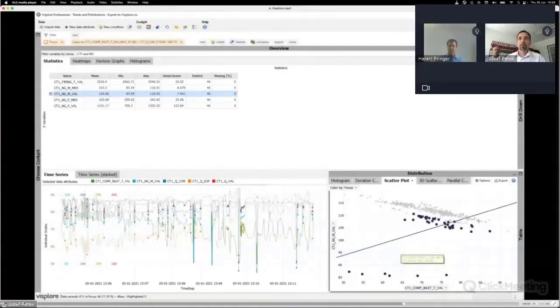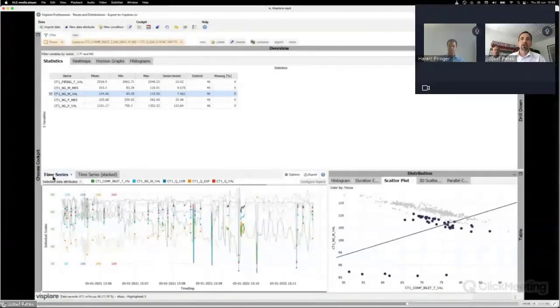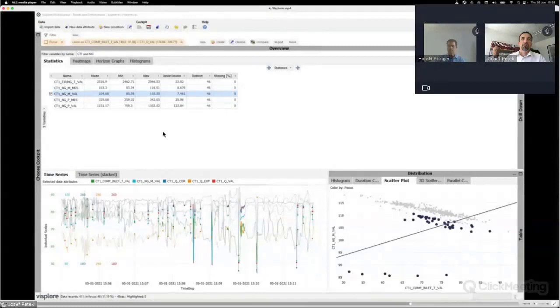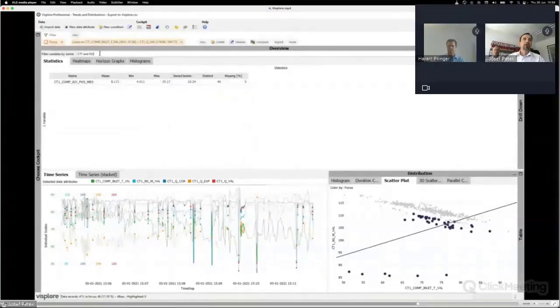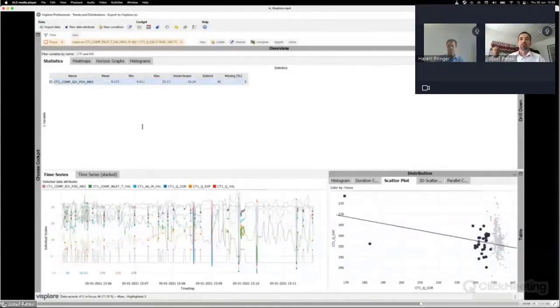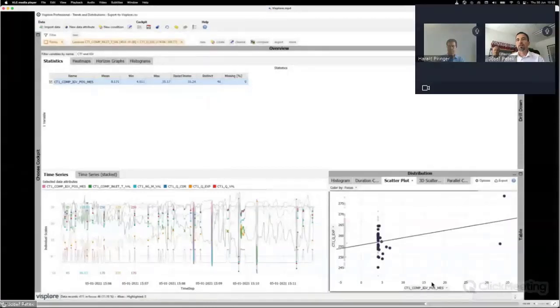which basically proves that we have a systematic problem here. It's not just a problem of one single power measurement. So we dig in further, and one parameter to look at next would be the so-called IGV angle. The IGV angle is very much related to the control system of the gas turbine. For full load operation, the IGV angle is expected to be at full open position. So to double check, we again generate a graph.